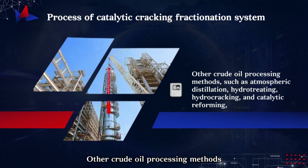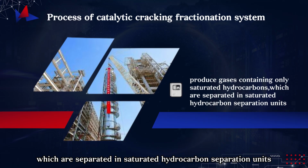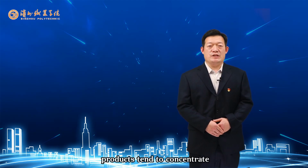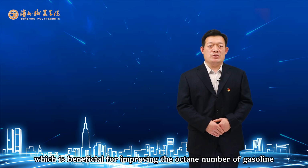Other crude oil processing methods, such as atmospheric distillation, hydrotreating, hydrocracking, and catalytic reforming, produce gases containing only saturated hydrocarbons, which are separated in saturated hydrocarbon separation units. Aromatic hydrocarbons in catalytic cracking products tend to concentrate, and the proportion of benzene rings in the molecular structure tends to increase, which is beneficial for improving the octane number of gasoline.